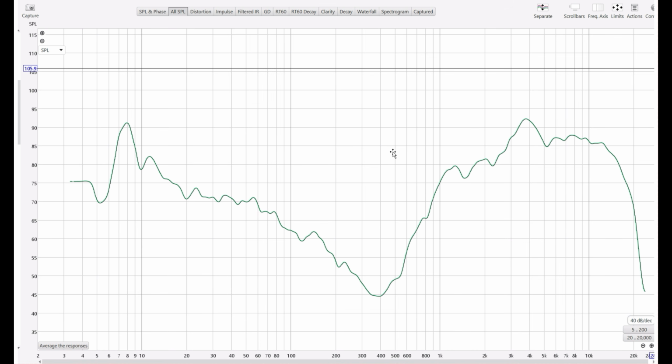But anyway, that aside, when we do a full range measure, we can see where these upper and lower limits are. This is where we're asking the tweeter to play higher than it can, and you can see the output just drops off, because you've reached the cone breakup area of that tweeter. It cannot vibrate any faster than that. This particular one drops off at 14,000 hertz or whatever it is, and same on the low end.